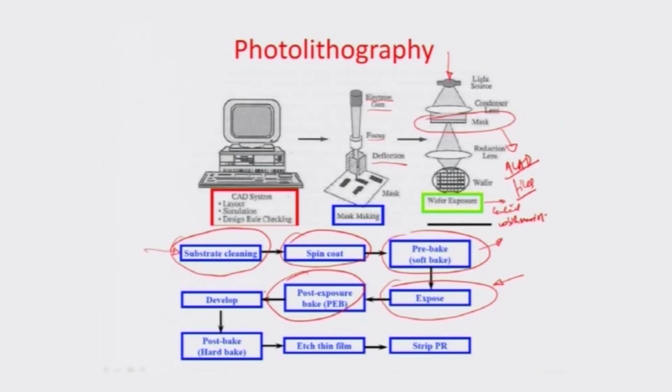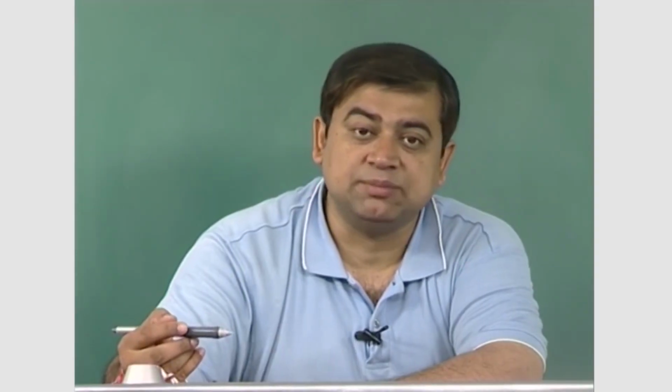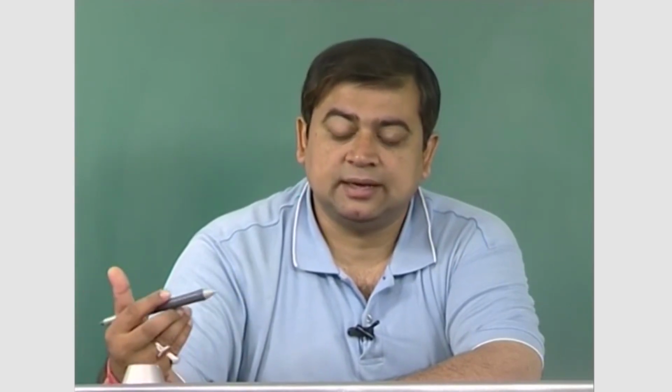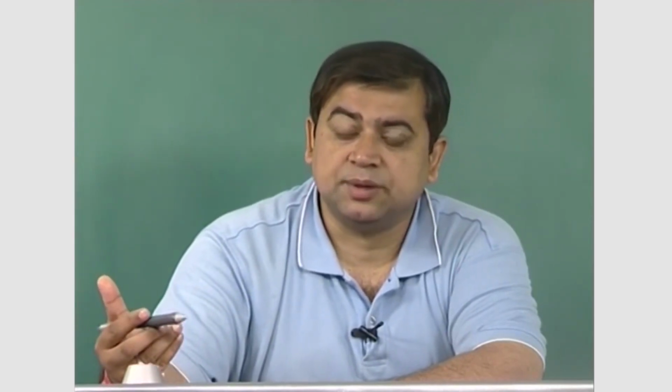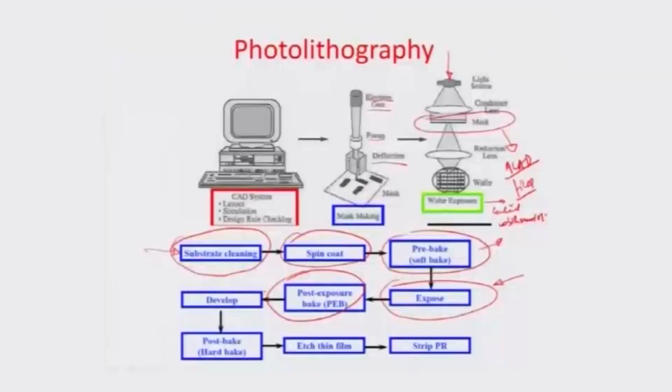The photo exposure process typically is either a cross-bonding or a debonding process, and the bond initiation in the polymer matrix actually gets either enhanced because of heat, or sometimes bond breakage becomes enhanced because of heat. So, heat is a catalyst which acts to speed up the reaction, depending on the way that the photoresist is developed or exposed.